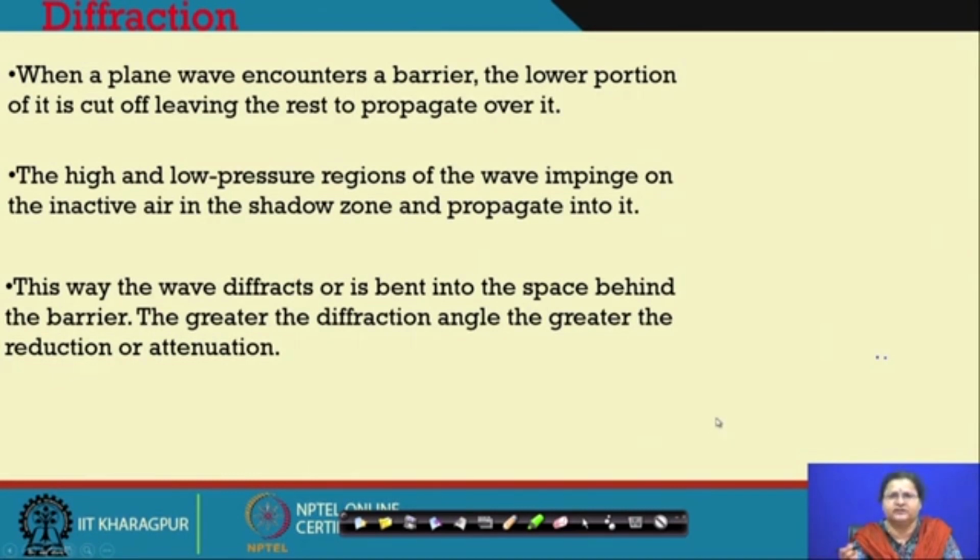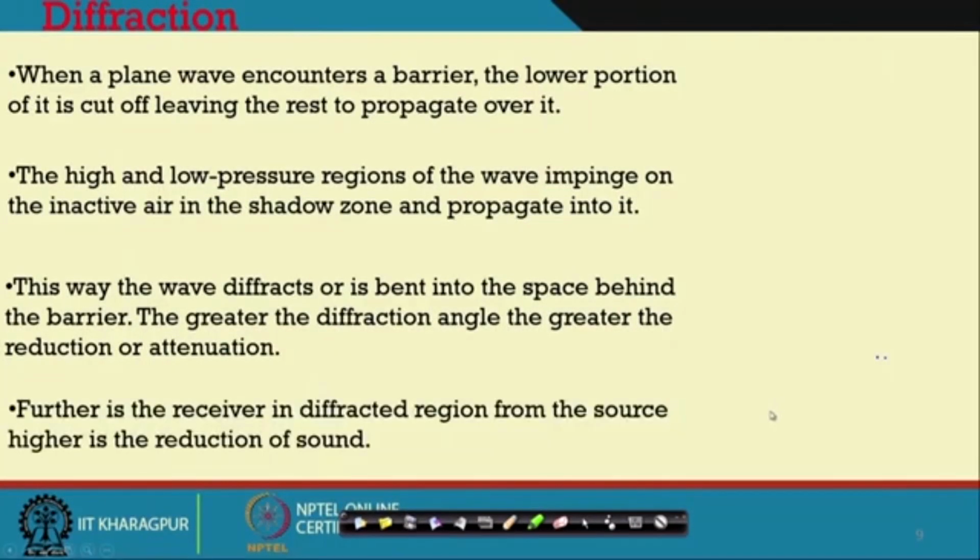The greater the diffraction angle, the greater the reduction or attenuation of sound will happen. So, if you are far, obviously you will receive lesser and lesser amount of sound, but yes, you will get something, that is because of the phenomena of diffraction. So, the further the receiver in the diffracted region from the source, the higher is the reduction of sound.